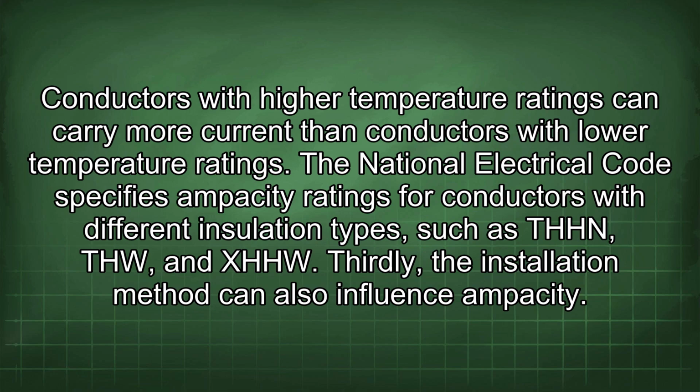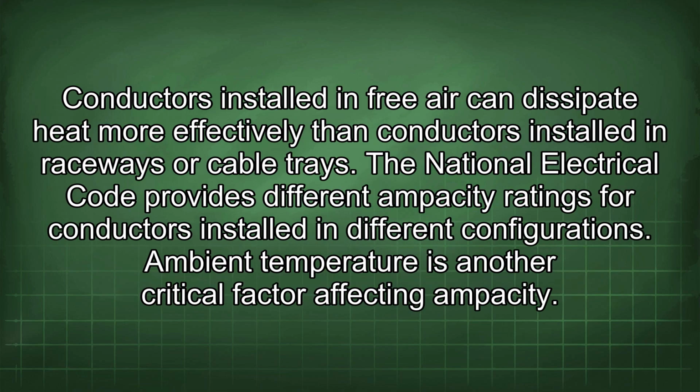Thirdly, the installation method can also influence ampacity. Conductors installed in free air can dissipate heat more effectively than conductors installed in raceways or cable trays. The National Electrical Code provides different ampacity ratings for conductors installed in different configurations.